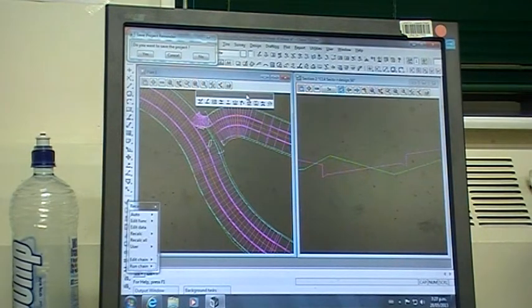You need a rainfall intensity that comes from a preset council standard. You need an area, and then it gets divided by 360. Okay. Using that and the Colebrook White for pipe roughness and the grades of the pipelines, 12D will size all the pipes within a pipe reticulation system.